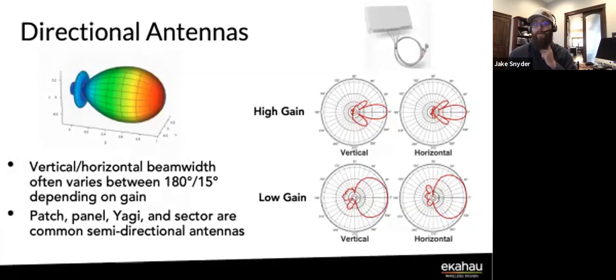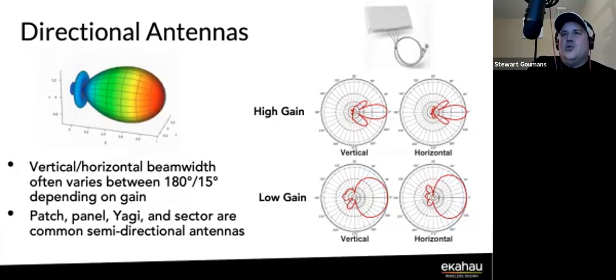that can be a problem for people directly under an antenna. Monopoles can sometimes give you a little bit of gain or fill that hole in, so that you don't get into that cone of silence, right? Yep. Exactly. That cone of silence. And that's where it comes into the directional, right? Those patch antennas are great for getting down those corridors.